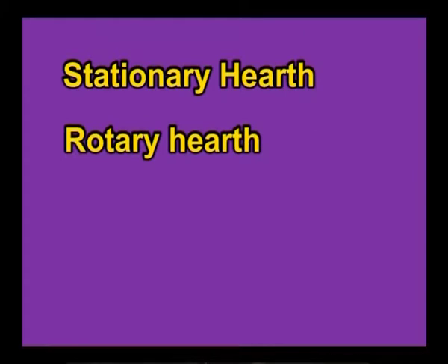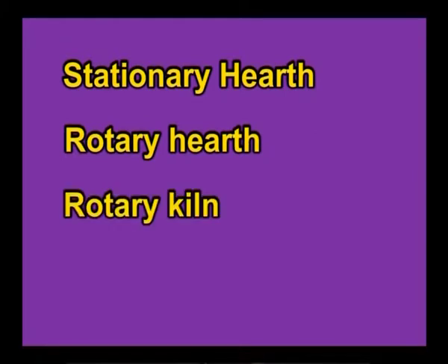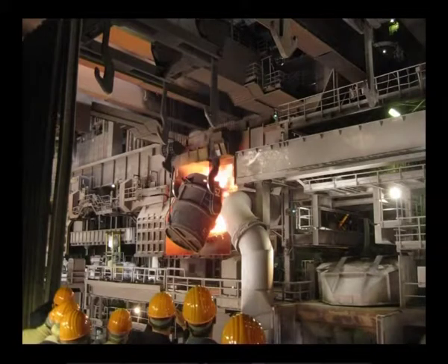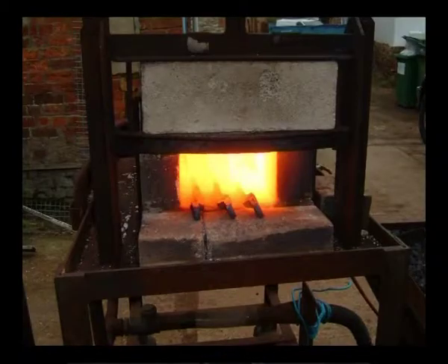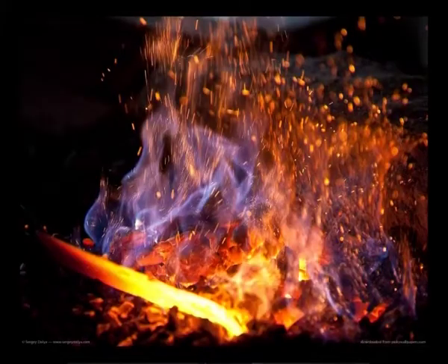The other type is the stationary hearth system. Those incinerator furnace systems that operate without grates include the stationary hearth, rotary hearth and rotary kiln. The stationary hearth is usually a refractory floor to the furnace, which may have openings for the admission of air under slight pressure below the burning material on the hearth, in the manner of the blacksmith's forge.